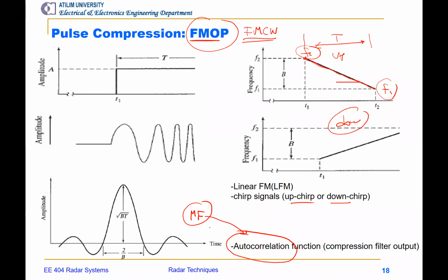So we simply correlate the received signal with itself, actually. Remember again the impulse response of the matched filter. It was x complex conjugate of T minus TR, right? So if I convolve the received signal with h of t, that's going to be a convolution, which will be autocorrelation when I choose this TR appropriately. So it's just like autocorrelation.